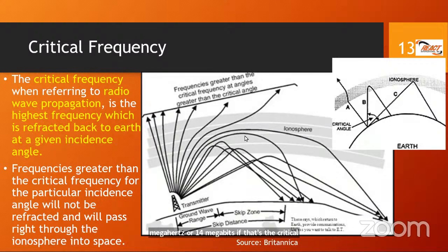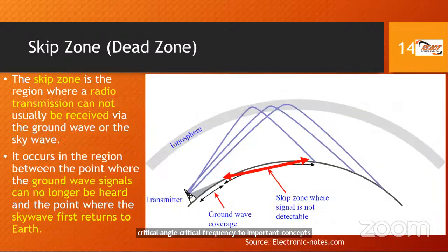So notice all of these signals here are being refracted back, all of these here. But notice these are in fact going into space. It's not being refracted back. So critical angle, critical frequency, two important concepts that we need to be aware of, and they're exam questions.